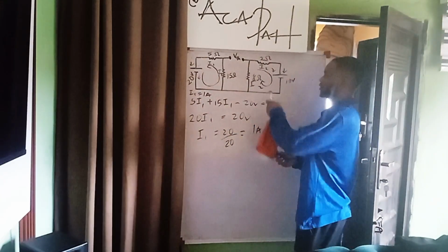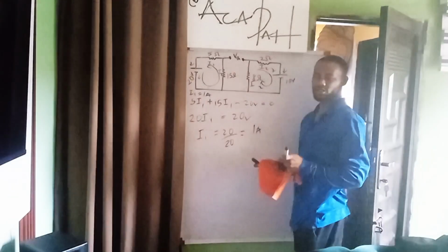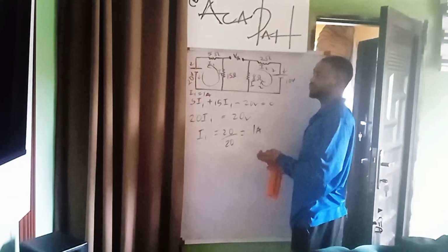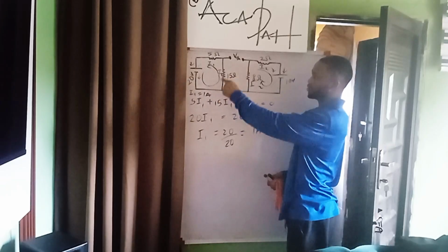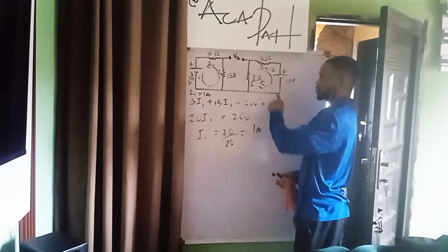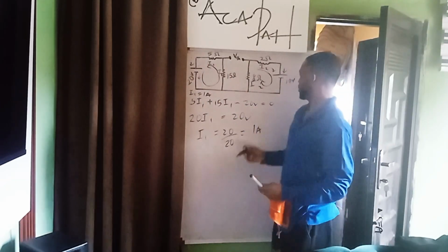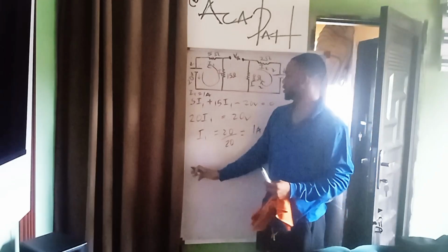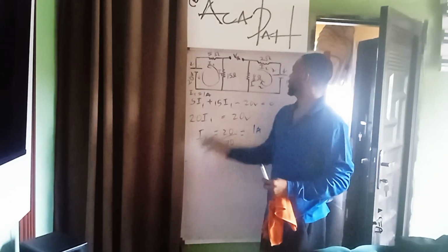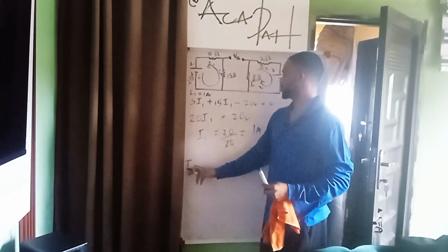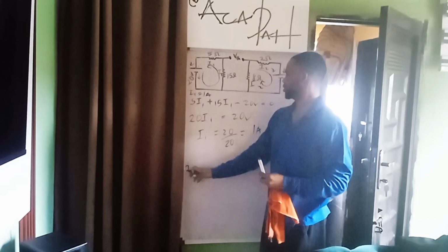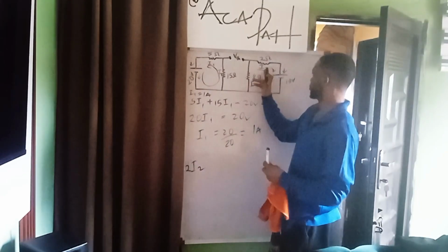Now for this I2, this is how to go about Thevenin. For Thevenin, you use loop analysis. You assume the same current flows inside the loop because it can't continue. So you come to this one for the I2. I'll do the same thing. For I2, I'll say I have the current entering. This current will be I2.